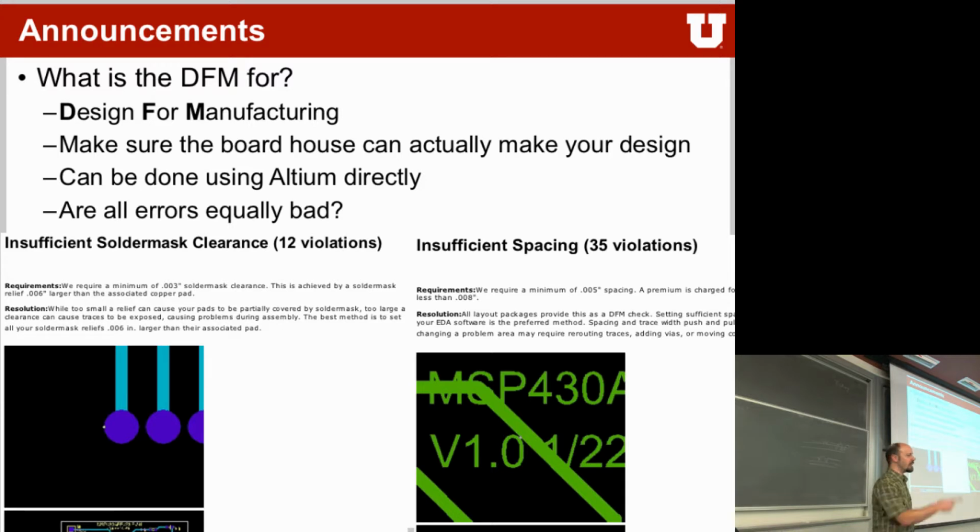Then we need to exit the solder mask on the hole. I'm sorry? I mean when we need to put the solder mask on the hole. You only put solder mask on top of the hole if you want to cover it up. So that's when you don't want to solder anything to it. Then you can put solder mask on top of a hole. And that's usually called tenting.